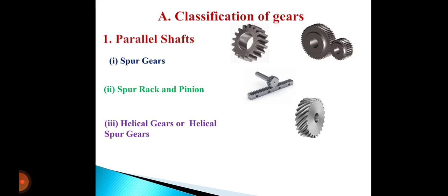Helical gears have the disadvantage of having end thrust, as there is a force component along the gear axis. The bearings and the assemblies mounting the helical gears must be able to withstand thrust loads.